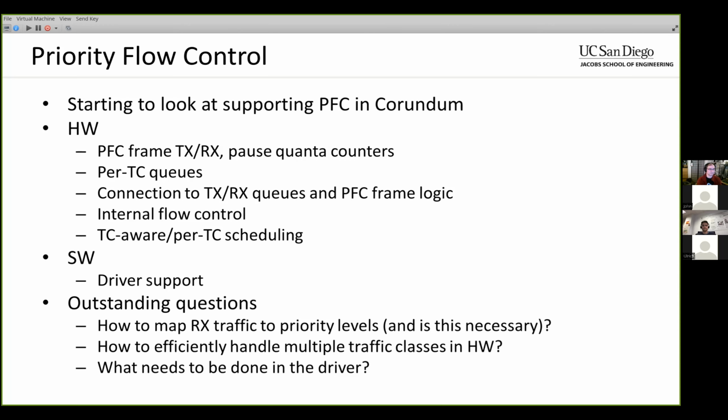In a MAC control module that will receive a request from the MAC client, which is congested, this MAC client will send a request asking this MAC control module to send a pause frame to the transmitting side. So that's the idea. Well, I've been looking into the documentation and I have to parse the MAC address. There's a specific value for that MAC address, in which case the priority flow control frame is sent. And right now I'm working on the implementation details in the finite state machine and seeing how to parse the signals.